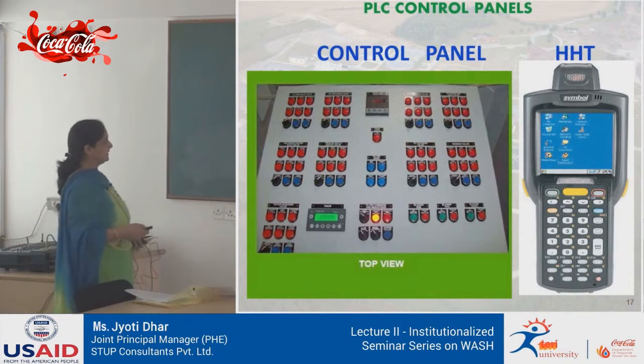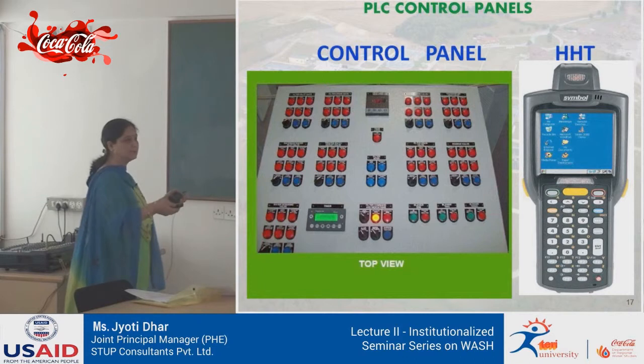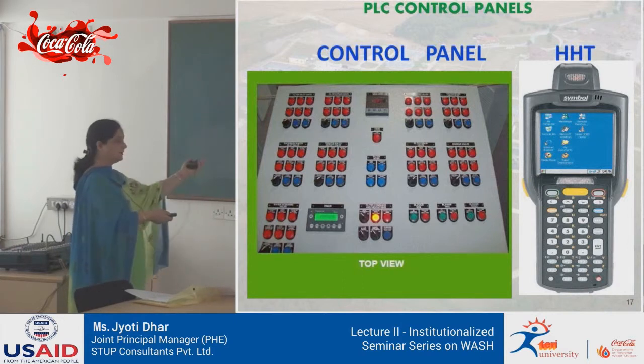Then you have a control panel. You have an input. Basically what is SCADA or what is PLC, programmable logic? It's an input, it's a processing device and then you have an output device. Input may be in the form of selector switches, push buttons or keyboard.